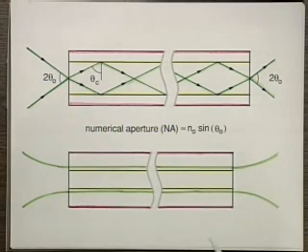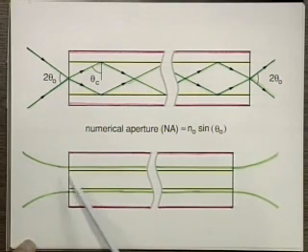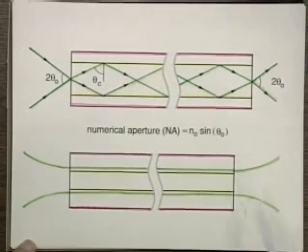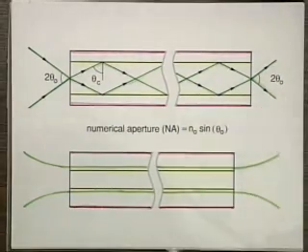If you look at the true picture, what happens actually, you bring in light that you focus into the core, even though it spills over the core a little bit because of the evanescent wave, then it will propagate down the fiber and come out on the other side, almost like it came in. And this is very close to the diffraction angle, which is of the order of lambda over d, where d is the size, as we discussed early in this course. So even though it propagates as a collimated beam in the fiber, as soon as it leaves the fiber, it expands very, very rapidly. All right, so that's basically, in a simple way, how light propagates.